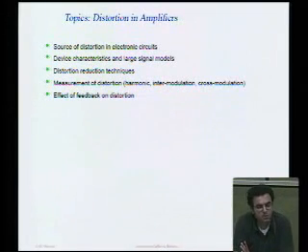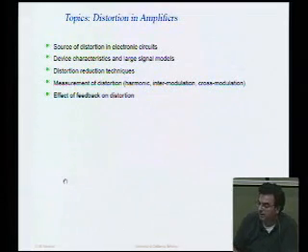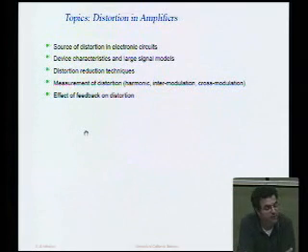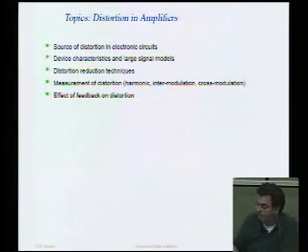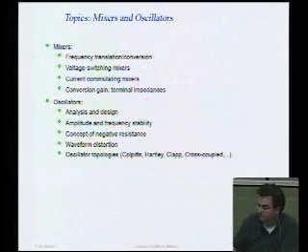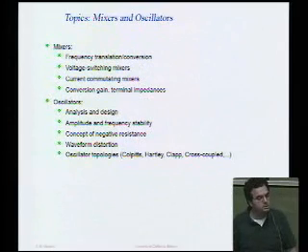What we'll find in this course is that there's actually quite a bit of nonlinear behavior, which is very important in communication systems, and we're going to analyze the distortion generated by these devices. We'll also look at how to reduce distortion, and feedback turns out to be a great way to reduce distortion, so we'll spend some time on that as well. Okay? So in some ways, amplifiers is something that you guys know. We're extending your knowledge, talking about distortion, noise, wideband operation.